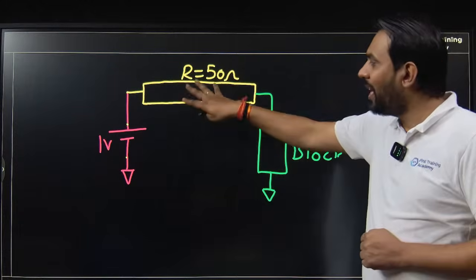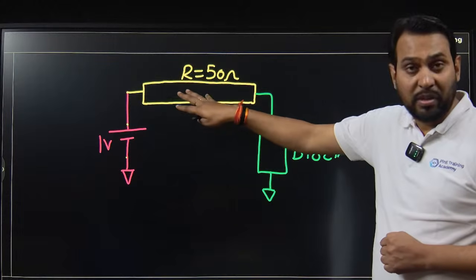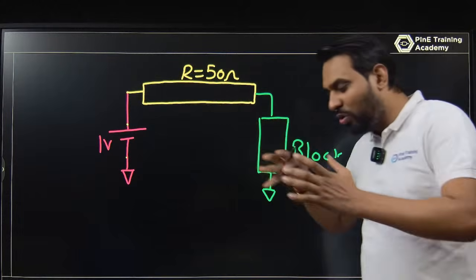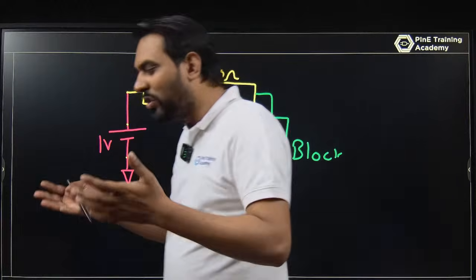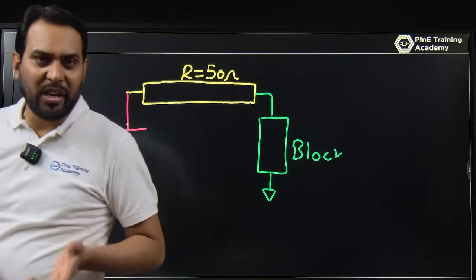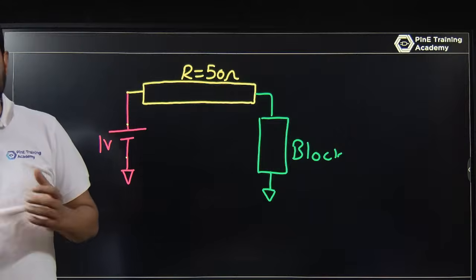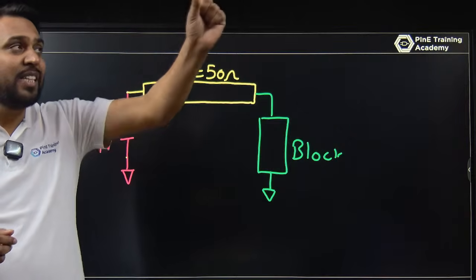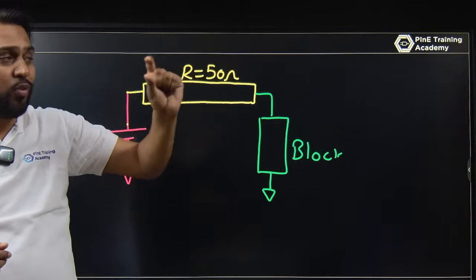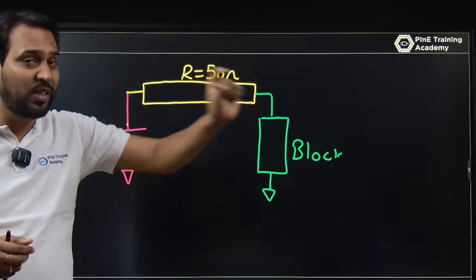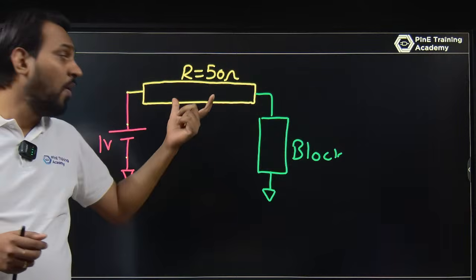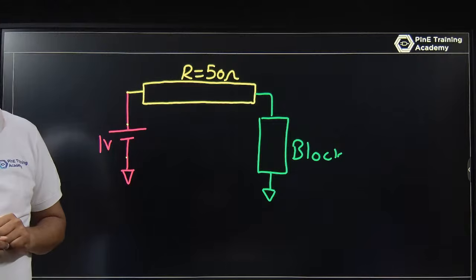By the calculation, by the DRM, the design rule manual, whichever technology you are using, everywhere we will find the DRM file. In a DRM file you will find, at this temperature and this value, the sheet resistance. On the basis of the sheet resistance you can calculate the value of the resistance.